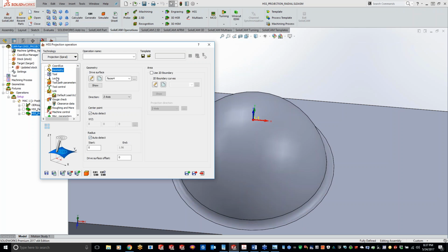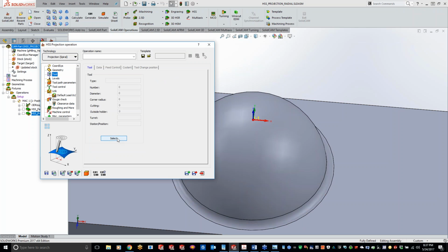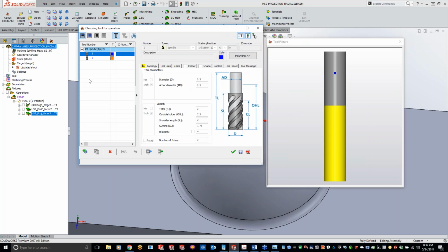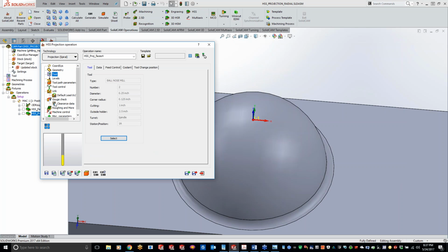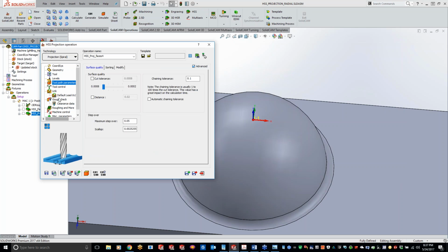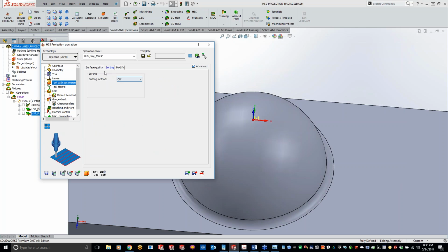And we'll do our auto detect again, so it's cutting right on the center. And we can go to our, oh, this one's automatic. I'm not going to have to switch it over to spiral. All I get is one option to do clockwise or counterclockwise because we're already doing a projection of spiral there. So let's do a save and calculate.